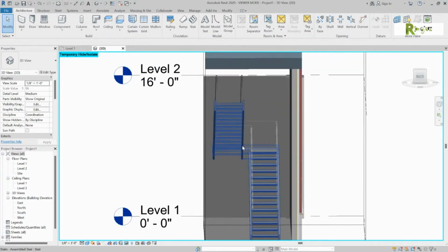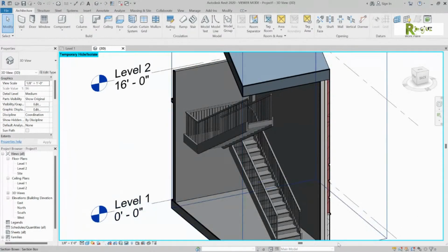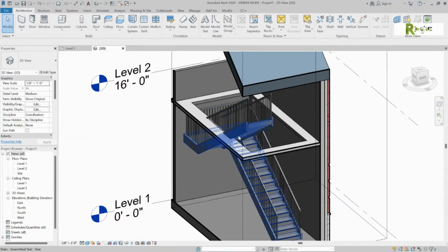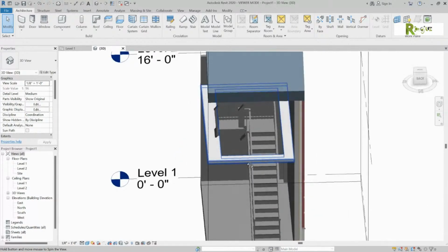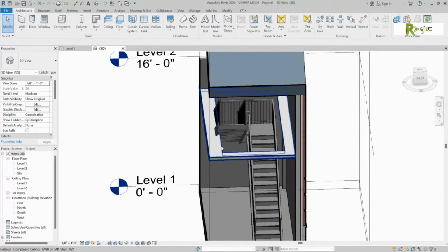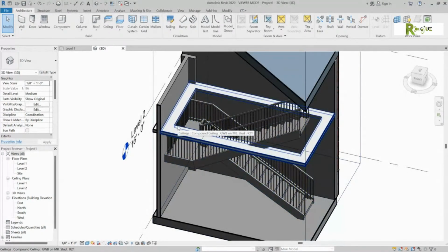Now, that HH, what that did was, do you see the cyan border around your view? Mm-hmm. It's telling you that you've got some things temporarily hidden. Do you remember where we did the shade? Down there at the bottom, there's a pair of sunglasses. That's it. And say reset. And then you'll see you almost got that in the right spot. It would have been nice to look at that view a little bit differently when you were drawing it, and you would have been able to hit it dead on.